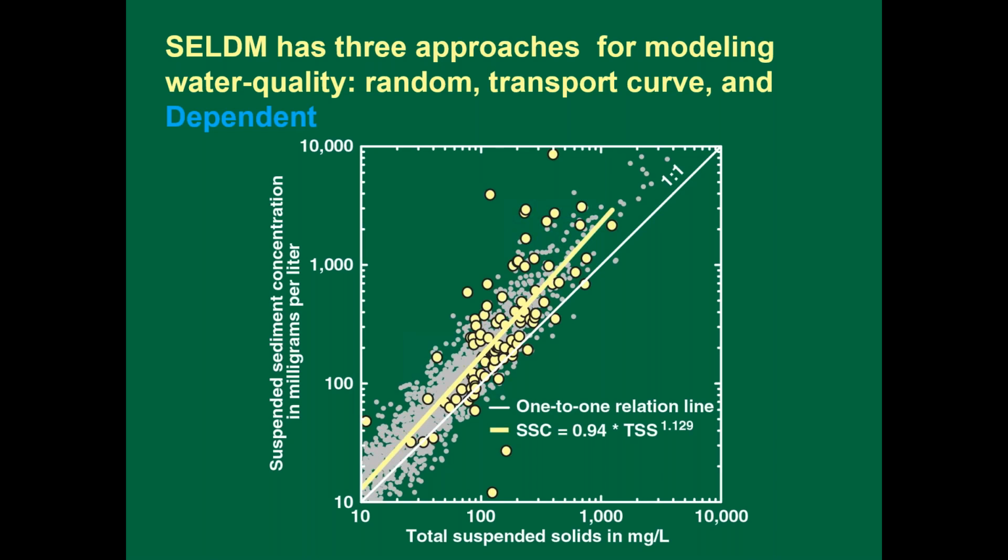So we come up with this relationship. Now, why would we do this? In highway runoff, there's 50 years of TSS measurements because TSS was selected, because TSS is good for measuring wastewater treatment plant effluent, but it's not great for stormwater. But because that was a regulatory constituent for wastewater treatment plants, it got co-opted for use in the stormwater realm.